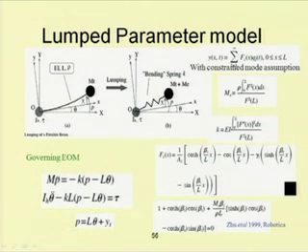So, the lumped mass present here is MT plus ME, and this is the bending spring. This ME can be obtained from this equation. Similarly, the stiffness K can be obtained from this equation, and the governing equation can be written in this form. These are brief hints given for deriving the equation.